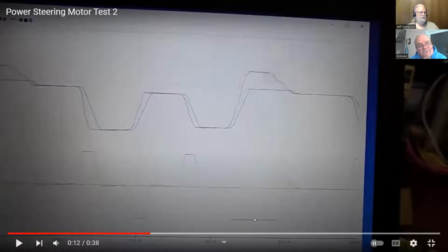So it says put this much power to the motor, and it's still saying continue to go. If that's up against the hard stop, it'd say, apply full power against that hard stop until it smashes something. But right here, if you listen to the audio, you'll hear the motor turns off because it went past that point. So just a couple of lines of code will save you from slamming it into the hard stop or pushing against the hard stop with full power of the motor.